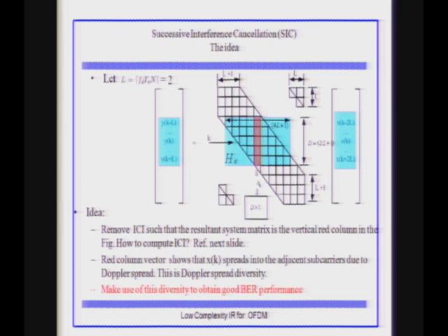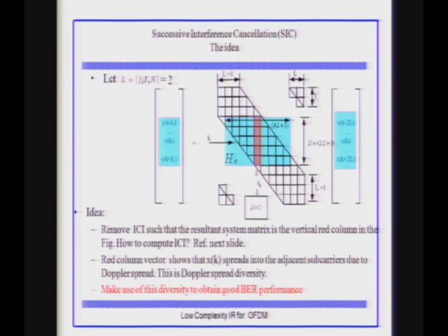Right. Okay, so make sure I understood that. I think what I was trying to gather from you is that what's also important is the interleavers, the symbol interleaver. Yeah, and that's what we discussed a few times, right? Interleavers are the ones that bring in gain because they introduce independent channels over the carriers. Yeah, I missed that point. You have a symbol interleaver that could randomize these, and that could add to the diversity. Having the interleaver there could help further on the diversity.